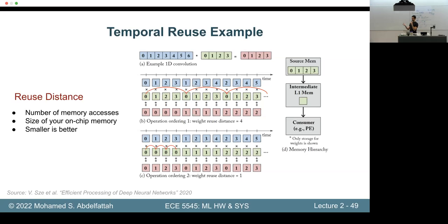because I do the computation and then I throw away the data and I need to refetch it from external memory. Another reason is, while this memory hierarchy here shows just one slot or one location for private memory or register, so it has one register per PE, if I have a large reuse distance, I can also get around that by having 4 registers per PE.